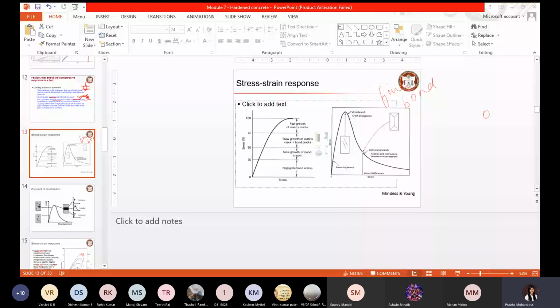Basically, when you change the type of concrete, you will be using different types of cement and different types of aggregates to obtain the required performance. That can be lightweight. If you are looking at lightweight concrete, you will be using different types of aggregates, which will help you reduce the weight of the concrete. If you are looking for high performance concrete, you will be using more SCMs in the concrete structures to get both strength and durability performance.